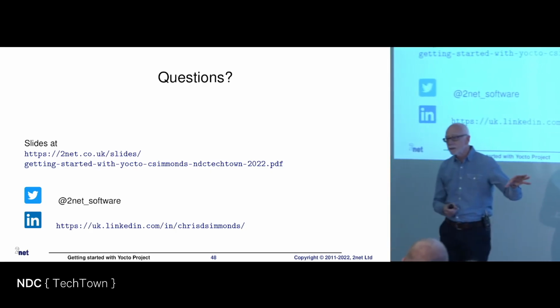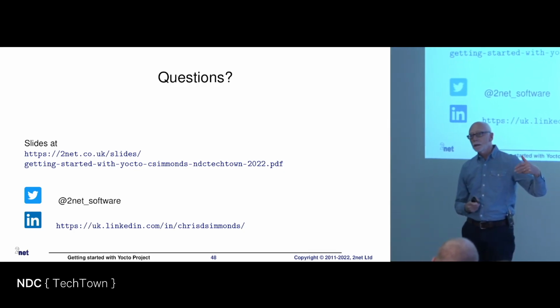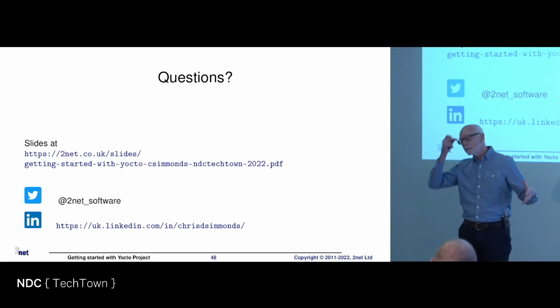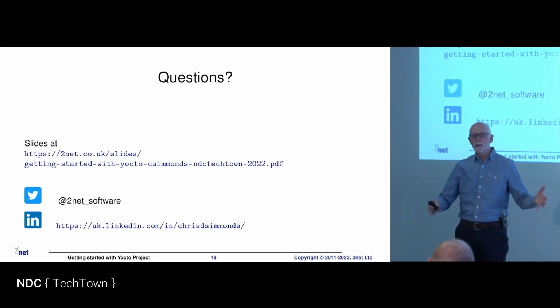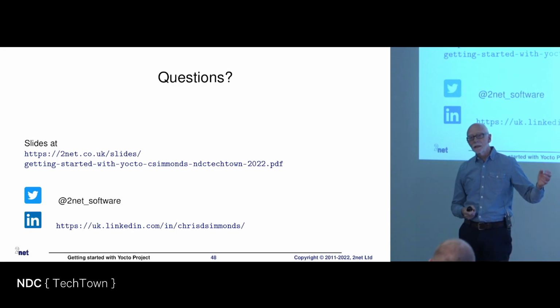The BSP recipe you have will, amongst other things, define the Linux kernel it's going to use. So if you get a recipe for an NXP IMX8, then that will use the Freescale kernel. If you get a recipe for Raspberry Pi, that will use the Raspberry Pi kernel, and so on. Generally speaking, the vendor kernel comes as part of the deal.